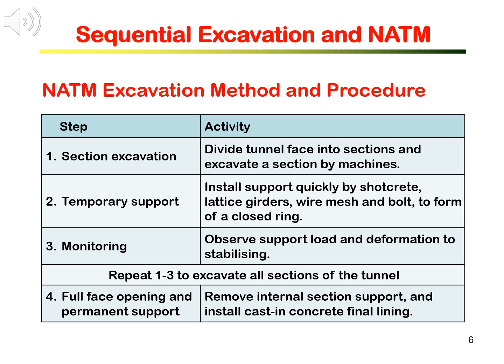In describing NATM as an excavation method, we mentioned that it involves the steps of sequential excavation and monitoring. The table here provides a summary of those excavation steps and activities. First, the tunnel is divided into sections, usually left-right symmetrical. Excavation is started with one section. Because of generally weak and poor ground, excavation is by excavators and machines.